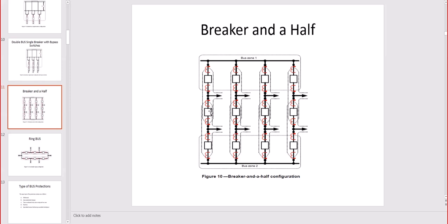So what's happening if we close the breaker? Well, all the short circuit power that goes to the feeders is doubled, right? Because we now feed from 2 buses, we will have double the available short circuit power, so you will need to size that feeder for that event, the kiloamps that you have there. So that's the disadvantage of having it permanently closed.